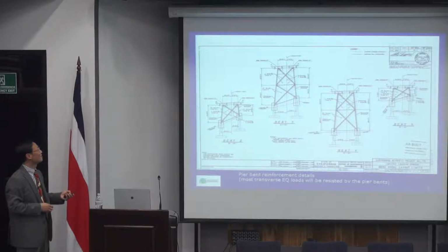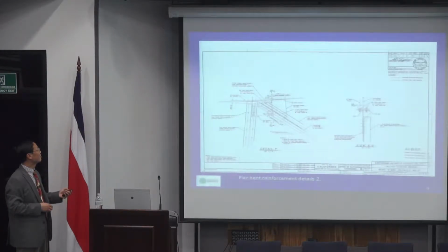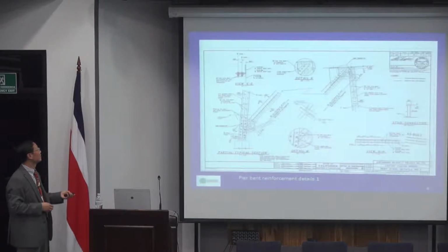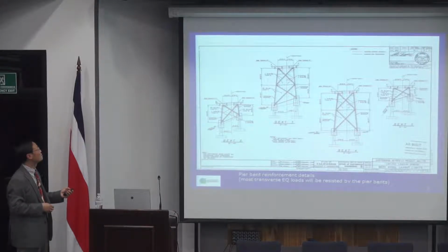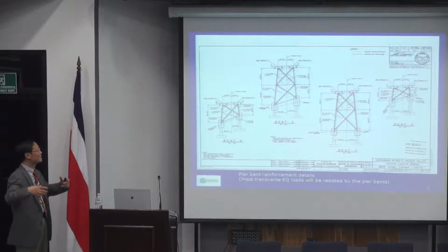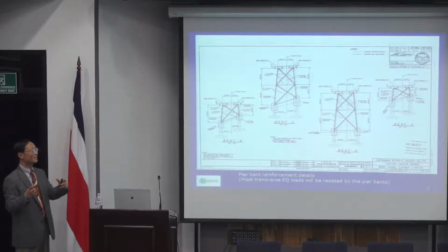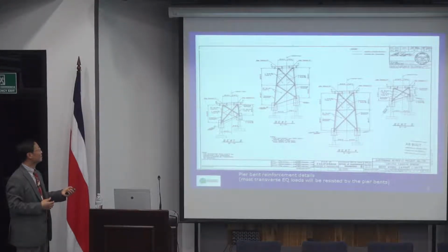In this case, if you make a rigid connection, it will be able to resist that torsional force. And again, I said, make it monolithic with a bigger concrete encasement that can resist all directions, even rotation, and very much that's a major concern.